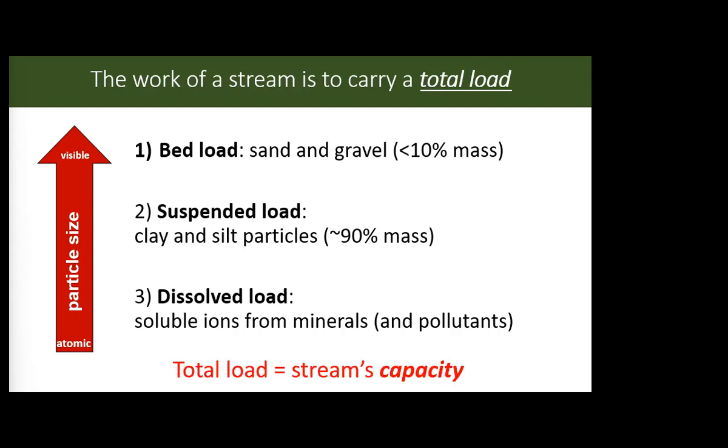So all of this added together is the entire stream's capacity. How much can the stream carry before it stops being a stream? As you can imagine, if we have so much sediment that the amount of sediment is greater than the amount of water, we're not going to move that sediment anywhere. So it ceases to be a stream at that point. It's all about how much it can move before we've reached the total capacity of motion.